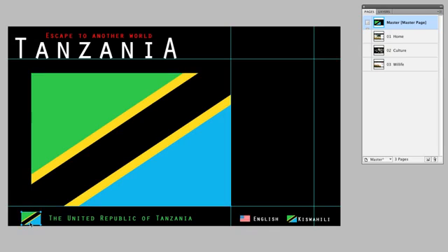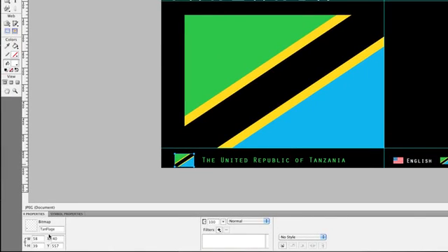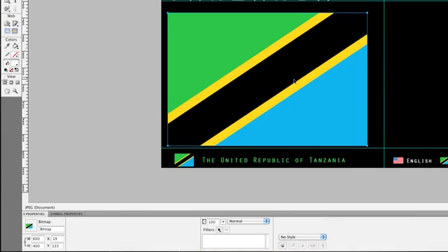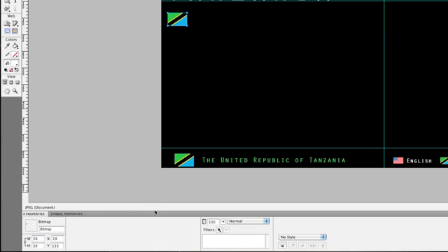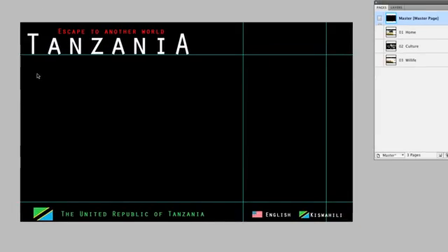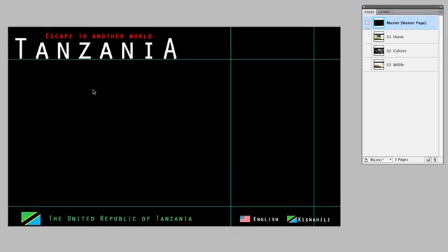So I went over, found out that the dimensions of this were 58 by 39. Now there is a little feature in Fireworks that I just adore. And this was scaled in proportion, so I want to have this scale in proportion. So it comes in 600 by 400, and all I have to do is come to the Properties panel here, make sure that that little dot is selected so that these two values are linked, and all I have to do is just type in the value for the width, and if I do that, it also scales to the height of 58 by 39. Very quickly done. Don't have to do it by eyeball. If I have the numbers, fabulous.